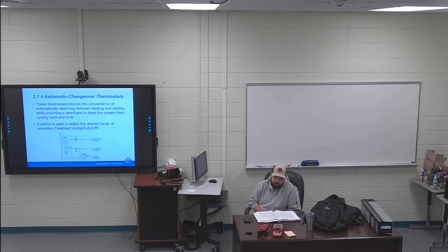The differential is normally 2 degrees. For example, if the heat set point is 70, the furnace will turn on at 70 degrees and run until the temperature is 72. So it's like, for instrumentation students, a buffer zone or a neutral zone that's put in an instrumentation loop. Next paragraph, first two sentences are also highlighted.